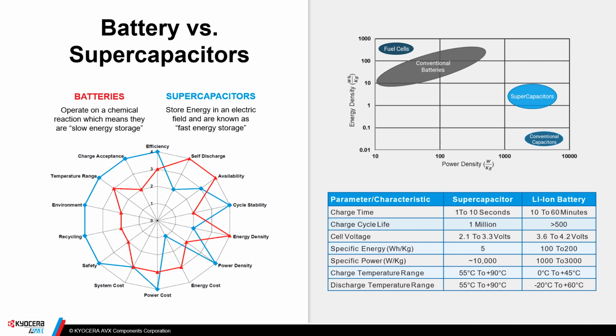That makes sense because supercaps have the ability to both sink a very large current when they're being charged or deliver a very large current when they're being discharged. So there are many different application notes on how to charge a fully discharged supercapacitor because, in theory, they might even destroy a power supply by drawing so much current. It's good to use those application notes to be safe in the charge of supercaps. At any rate, we can explain well the power density advantages of supercaps versus batteries.